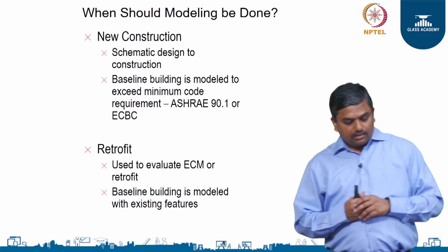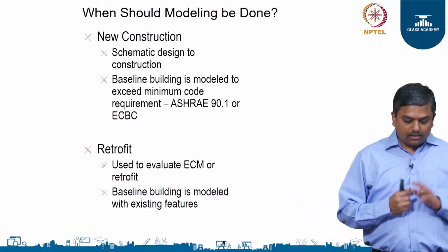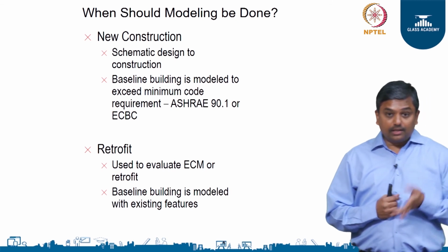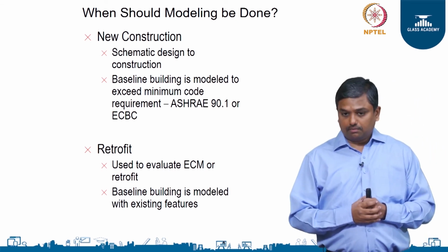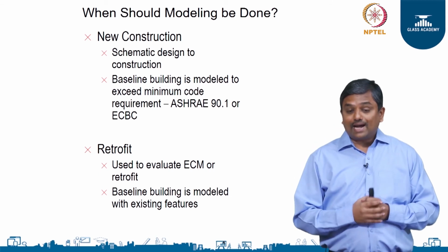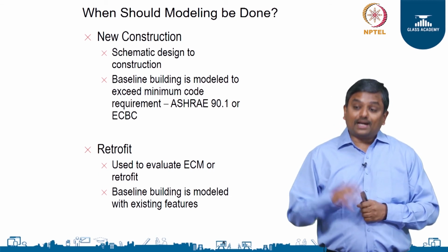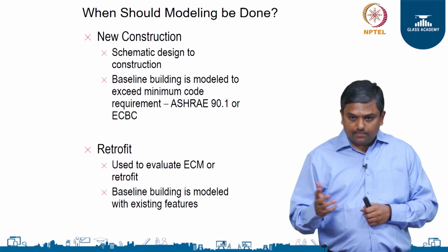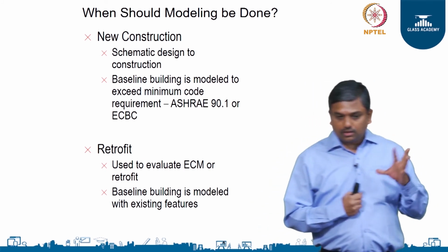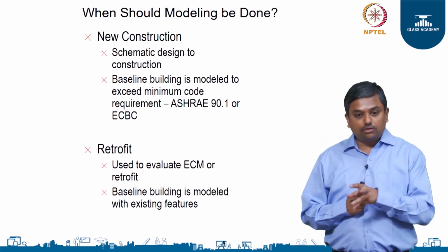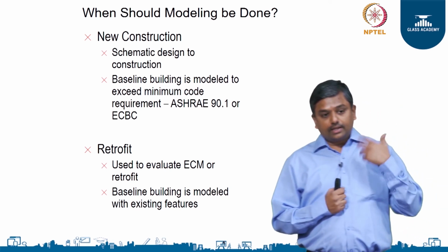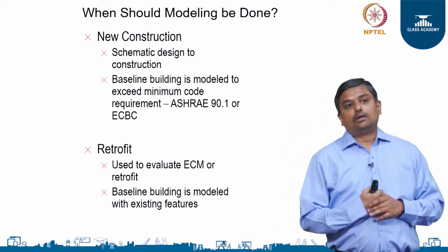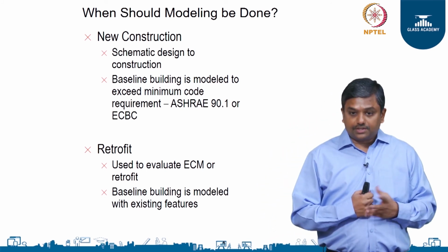A place where most of this energy modeling is very underutilized is in existing buildings. If you are able to create a building energy model for an existing building and calibrate it to the actual energy performance based on utility bills, then what you get is a computer model which reflects the actual performance of the building. And what this helps with is when we start doing energy audits of existing buildings, we come up with a lot of energy conservation measures.